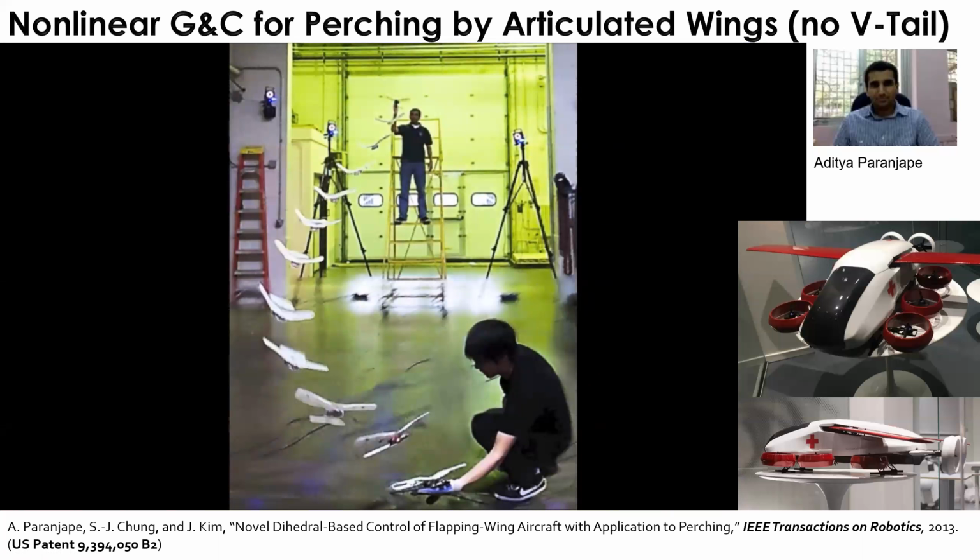So basically, a combination of a spectral normalized neural network trained offline and meta learning methods, so that we can actually update some of the weights in your neural network using a meta learning method. But here, you cannot do that. You cannot completely do real-time backpropagation to retrain the neural network. So what you're doing is you only train the last layer using some combination of adaptive control. So we are now demonstrating this NeuralFly method here.